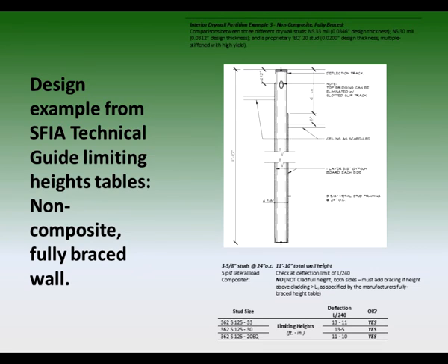These are not the only studs that could be used, but if you examine the chart, you will see that each meets the load and deflection criteria for the given wall height. All of them exceed the 11-foot, 10-inch wall height. This is a limited stud selection example because you would also need to consider any fire separation ratings or acoustic ratings that may be specified. But the main point here is that the only difference between a conventional stud and an EQ stud is the source for the limiting height data may be different. EQ limiting height data must always come from the manufacturer.